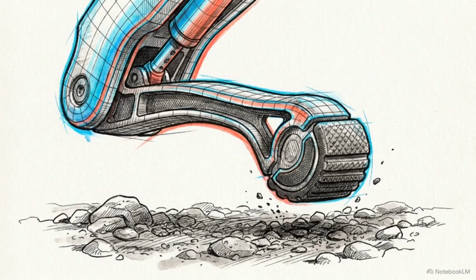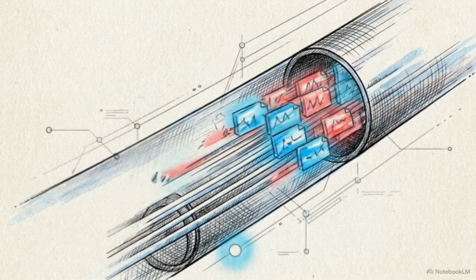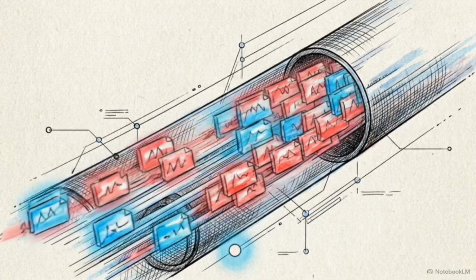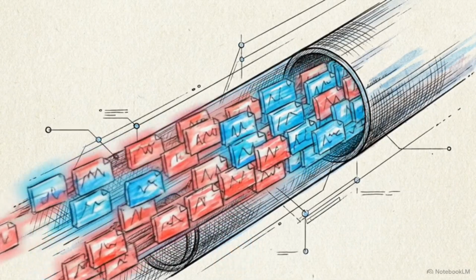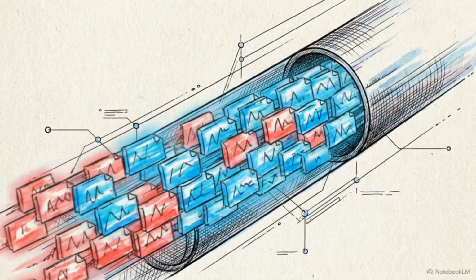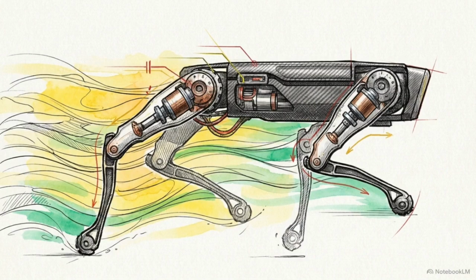Building an aware quadruped requires dividing the workload across a hierarchy of specialized plugins. World plugins monitor the entire environment, tracking global parameters like terrain friction across the simulation scene. Sensor plugins handle individual devices, processing low-level data like applying complementary filters to an IMU.